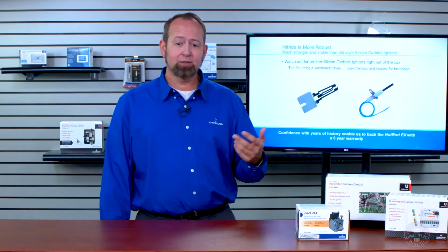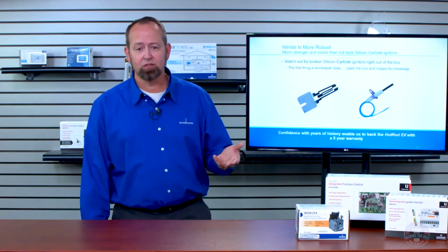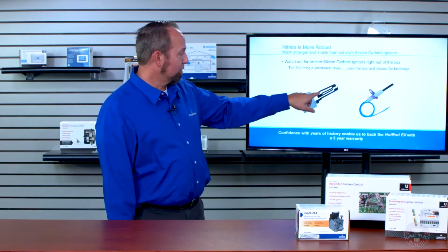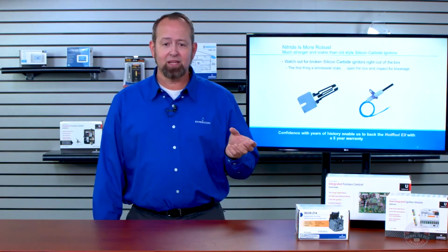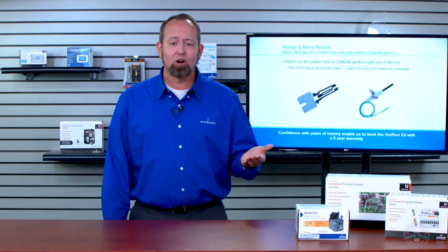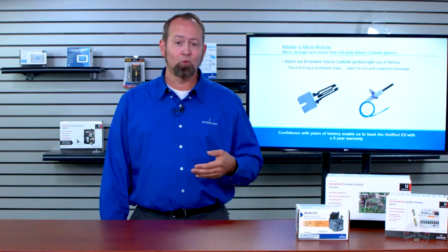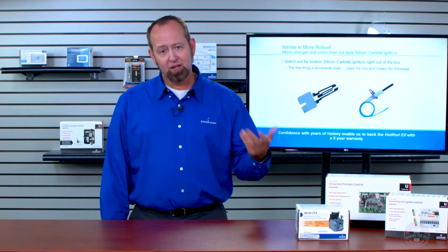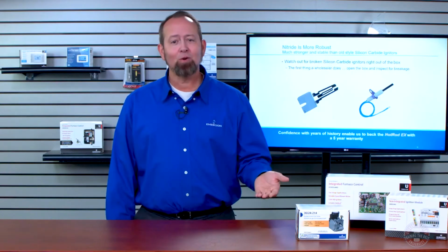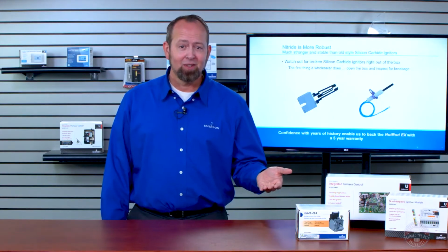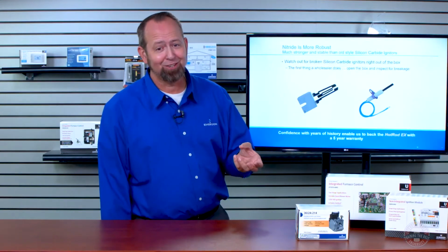The nitride is more robust. It's stronger than the silicon carbide, which I've already shared. The silicon carbide can break really easy. You want to make sure that it's a solid piece. If you're still buying silicon carbide, you need to check that when you're making the purchase. Open it up, verify that it's intact. Or buy a White Rogers Hot Rod Universal that you can see through the packaging and you can tell it's intact. You wouldn't even have to worry about that because of its strength.